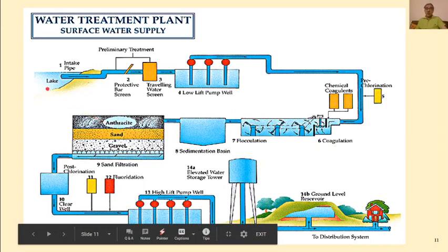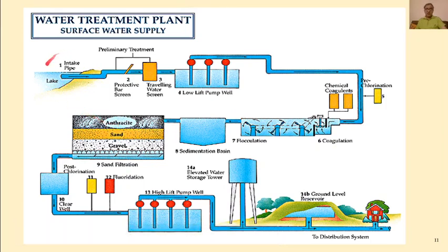Now this is the overall picture of one water treatment plant. From the intake pipe from a lake, we pass this water for preliminary treatment. The screens which I have told you about, the protective bar screens, will remove the suspended matter and all bigger waste present in the water from the lake. Then from